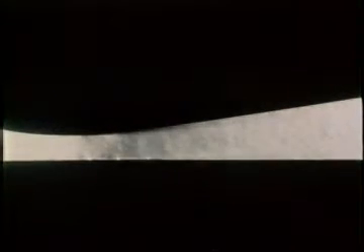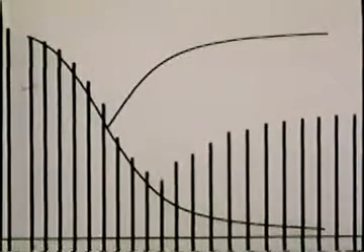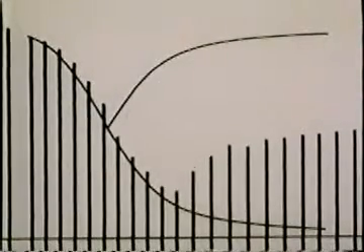The control valve is open just to the point of choking, and natural fluctuations in the flow do the rest. Thus, the Mach waves, the low sound level, and the pressure distribution all confirm that the lower theoretical branch downstream of the throat is supersonic, with the Mach number increasing from 1 as the channel area increases.